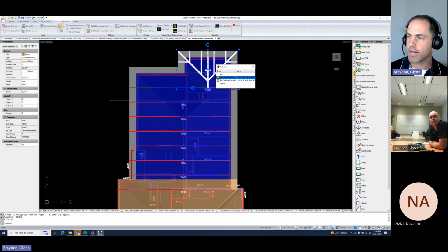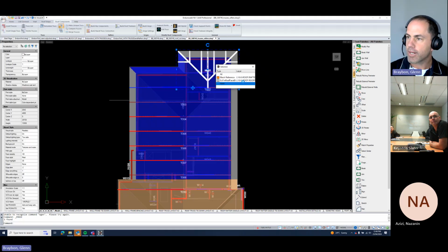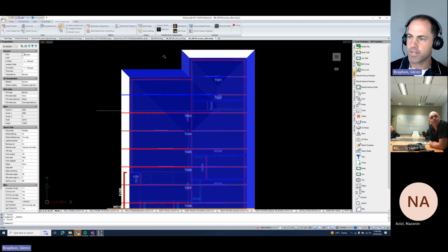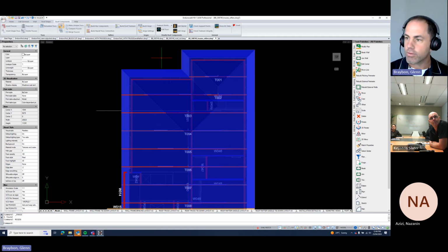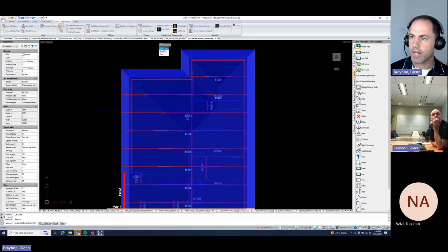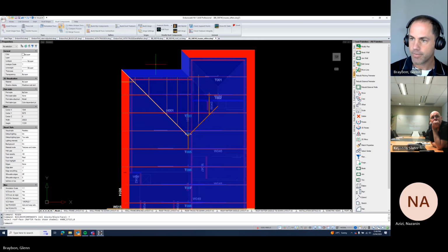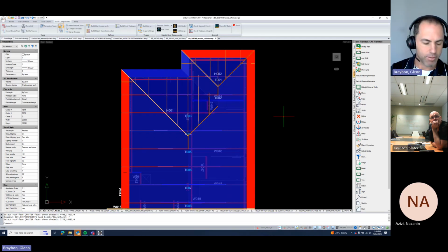Just look, there were a couple of errors in this job. That's probably why you've seen some different colours. I apologise for that. I'll try and keep the regen button going on repeat so we can look all square. So we've obviously got just two normal hip ends here. We're going to build the hip components on a face. Select here. Space bar. Didn't work. Build hip components. Face. Select there. Okay, so we've got two hip faces.